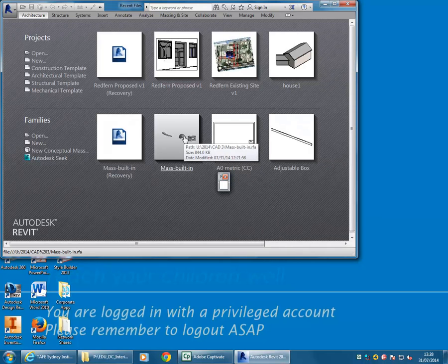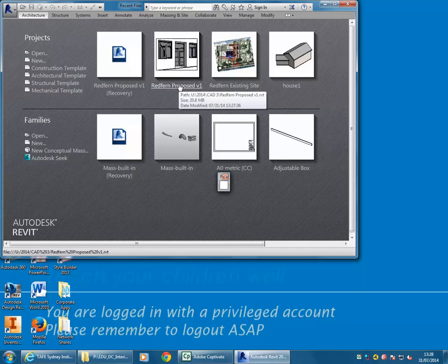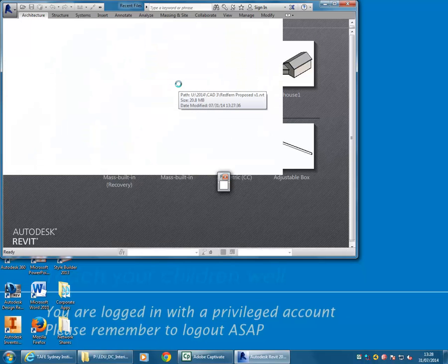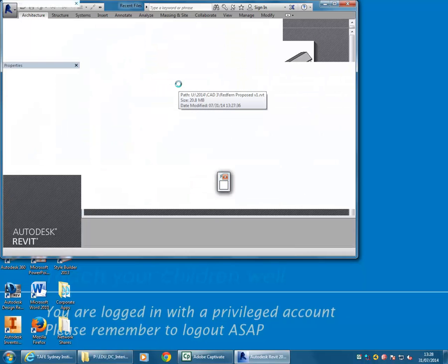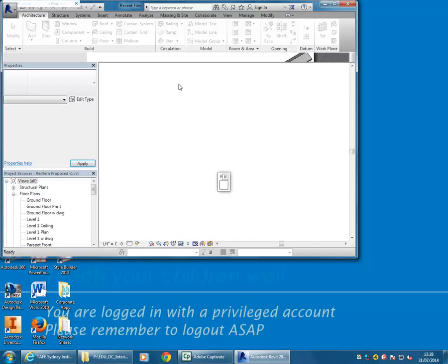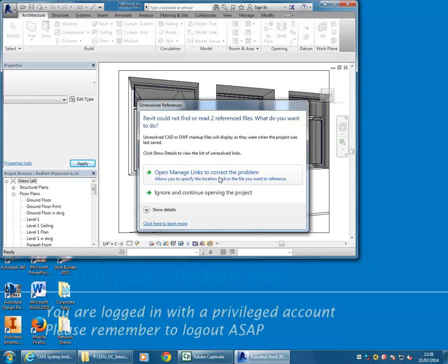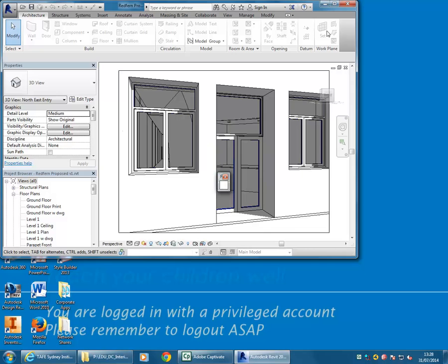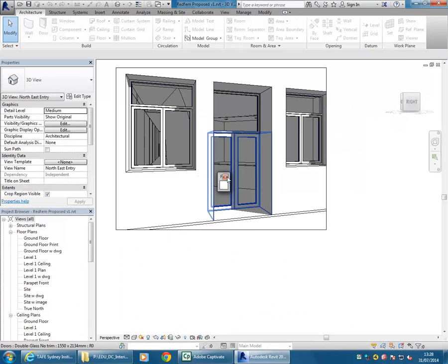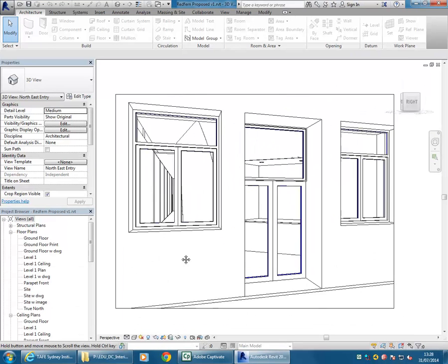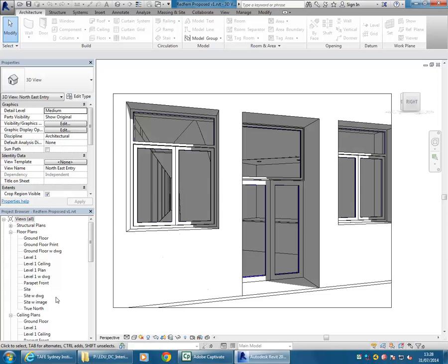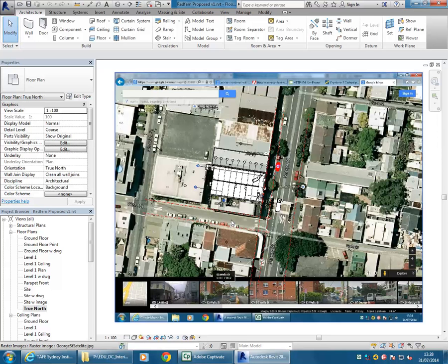Sorry, you just click OK there, and then you can turn shadows on down the bottom, down next to the sun. That's it. Okay, so there we are. That's all come back, and just make sure my true north is still set. Yep, that's all good.